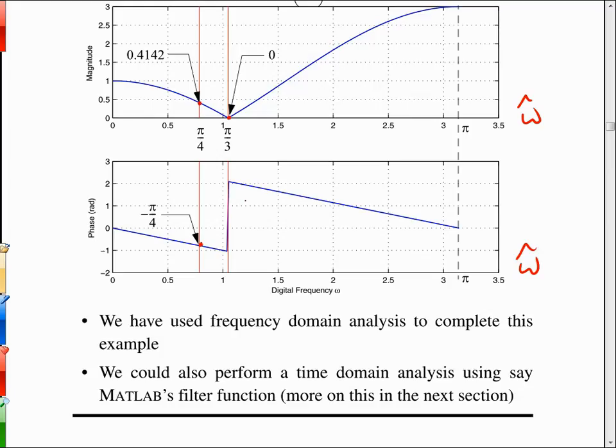But if you could put a filter at the front of the receiver that would annihilate just that one single frequency, you'd still have hopes then of getting something reasonable recovered, because your information probably spans a whole band of frequencies, and if you have to annihilate a jammer right in the middle of that, you'll take out a little bit of your signal, but not a whole lot of it.